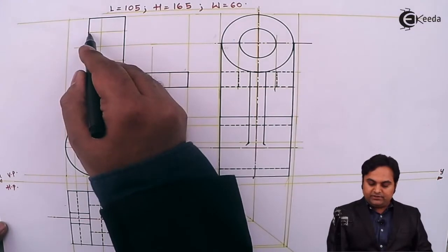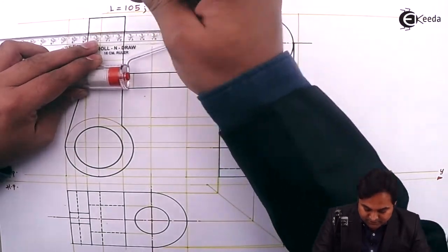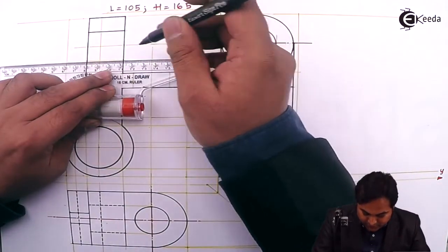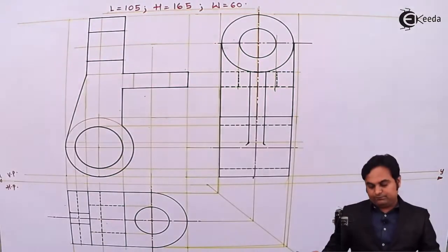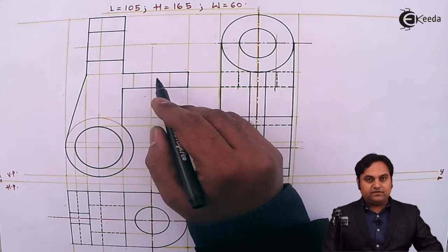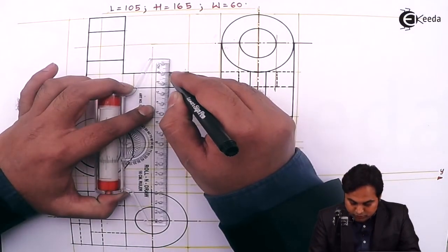So here I have to make this line dark because that cylinder has been cut, so this indicates the thickness. And even here at the bottom, then the circle which is there inside this portion in this plate, it has to be also drawn dark.